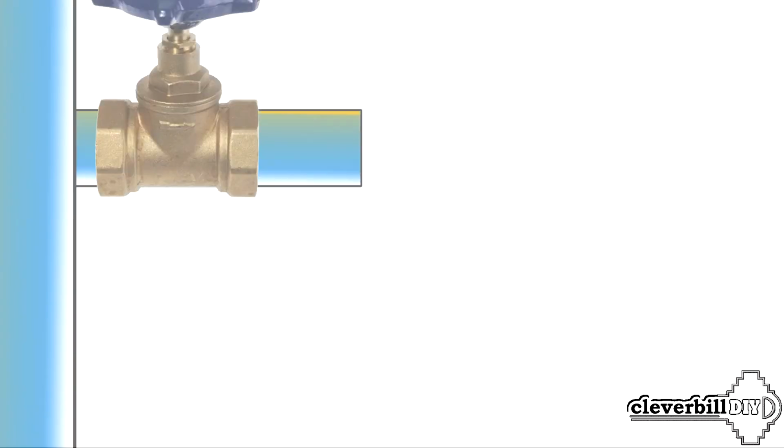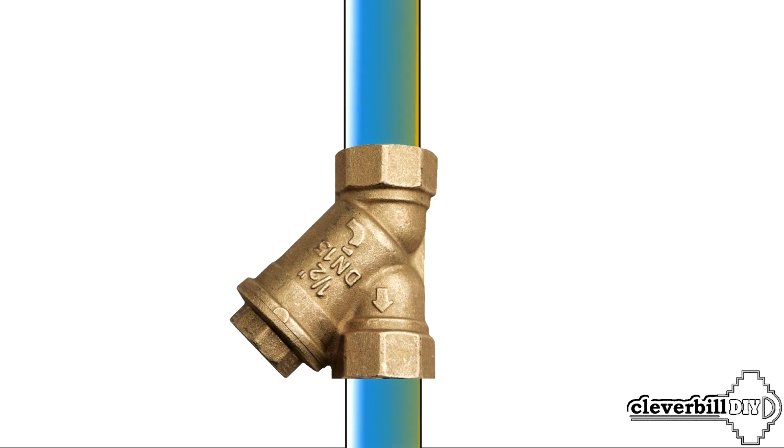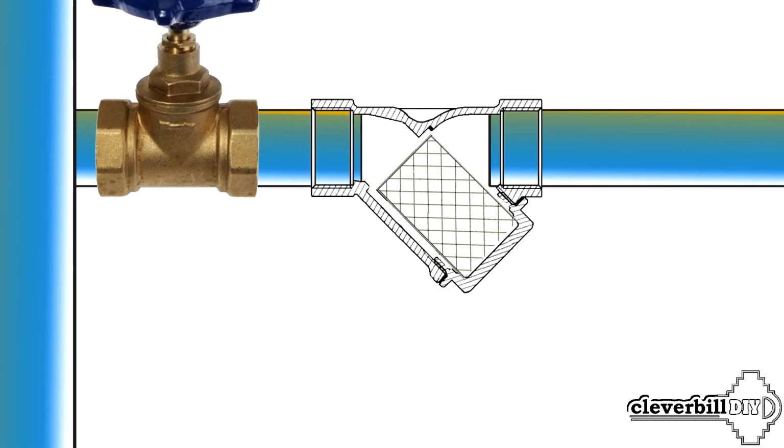Oblique filter. The oblique filter can be installed both horizontally and vertically, but at the same time, the filter plug should always look down. If the oblique filter is positioned vertically, the direction of water flow is only permissible from top to bottom. In an oblique filter, only a small part of the mesh adjacent to the point where the outlet channel overlaps is involved in cleaning. Therefore, compared to a straight filter, an oblique filter will have to be opened more often for cleaning.